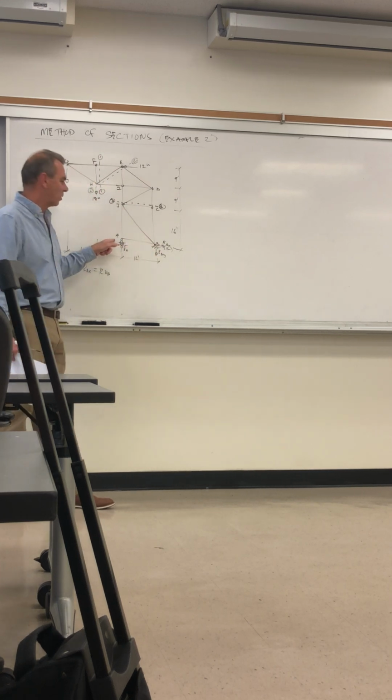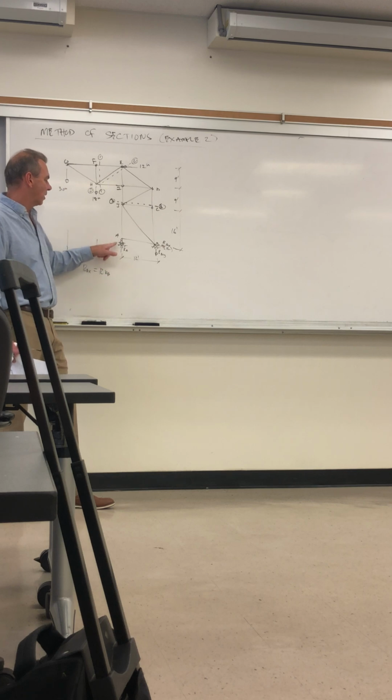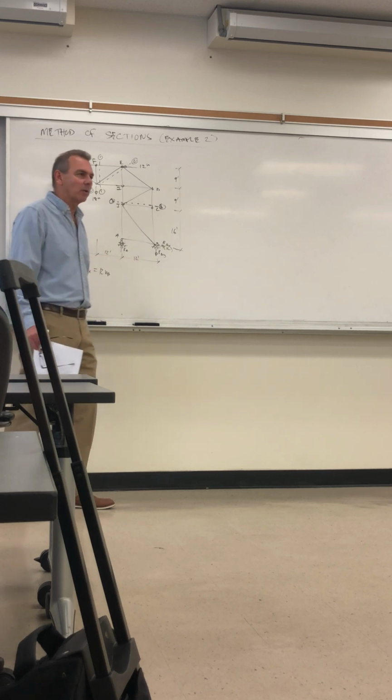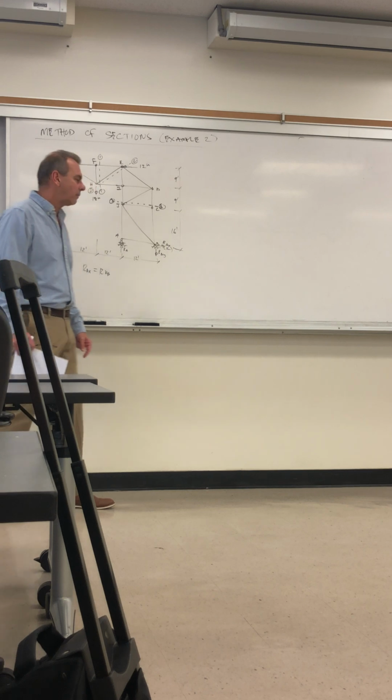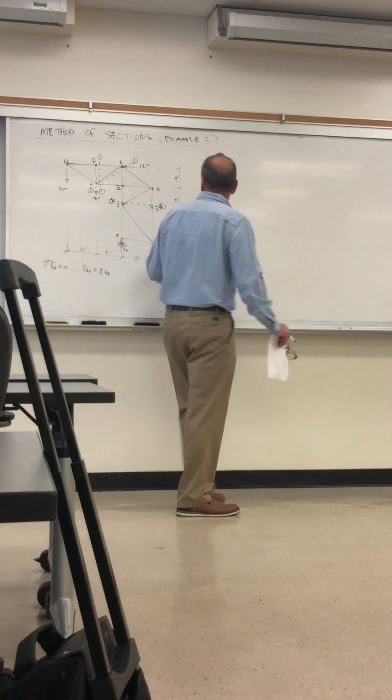And this one, horizontally, there'll be a small displacement due to deformations within the structure, but vertically this will be 0. So wherever there's a reaction, in the direction of the reaction, there's 0 displacement. That's why a reaction is shown. And then you can see I've drawn this down.